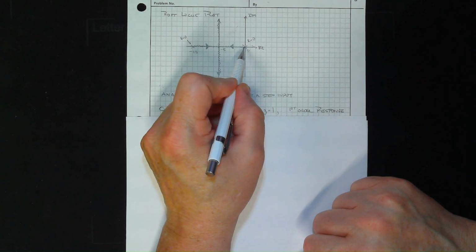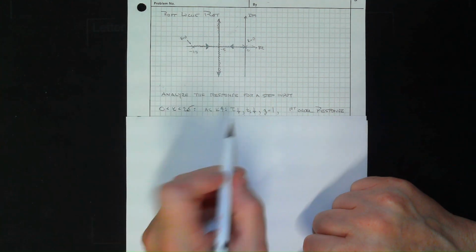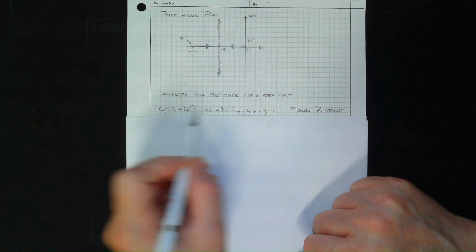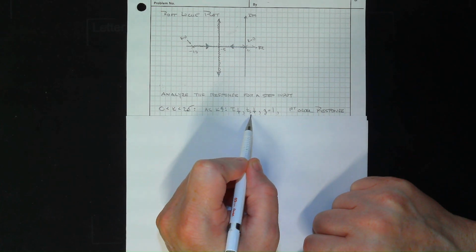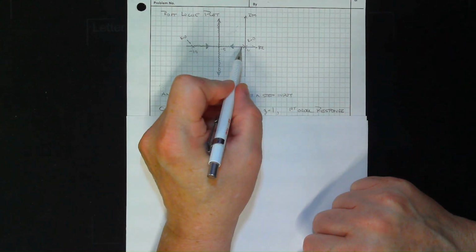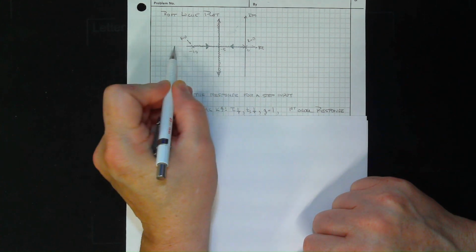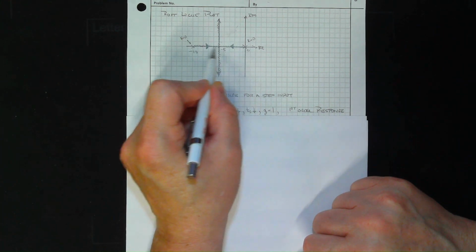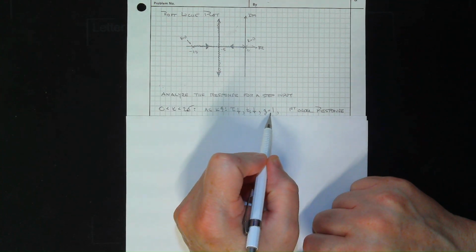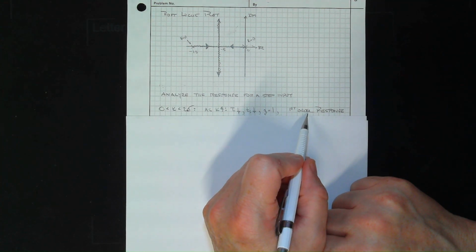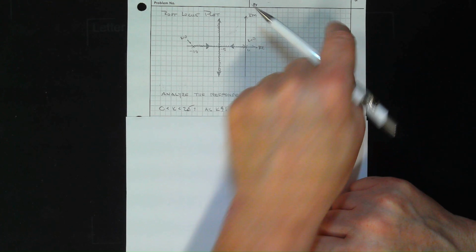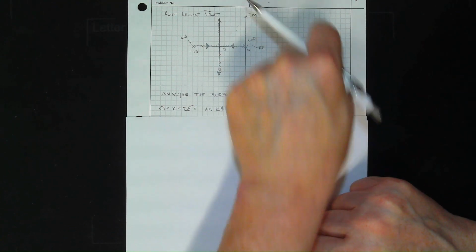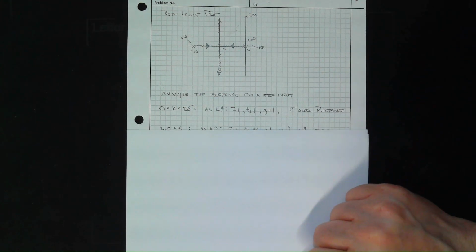So as it goes farther away from the imaginary axis, as k gets bigger, up to 2.5, time constant goes down, settling time goes down. But note the root is real the whole way. So all along here, the damping is 1. So the damping stays 1. That means the system is stable and you get a first order looking response. Okay, so it just goes nice and smooth like that. None of this.